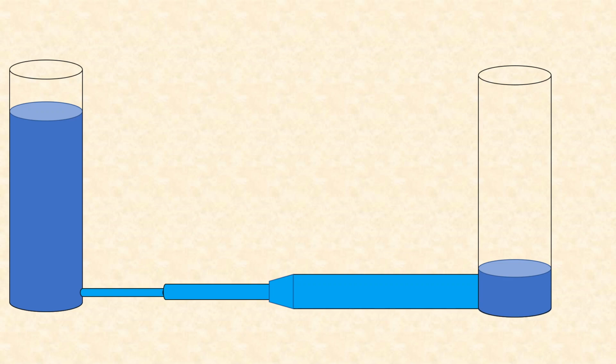In this case, if you consider the first pipe, the hydraulic gradient line will be somewhere around here, while the total energy line will be about here. Now as soon as it enters this bigger cross section of pipe, then energy will be lost, and again it will flow like this. The energy loss will be like this, the total energy.